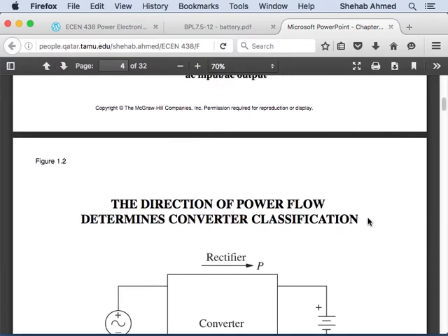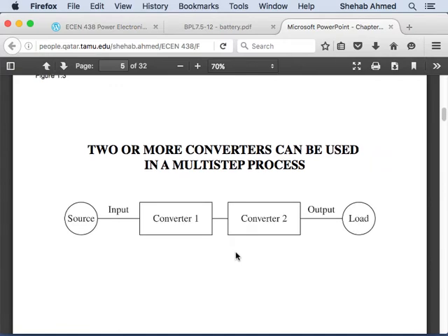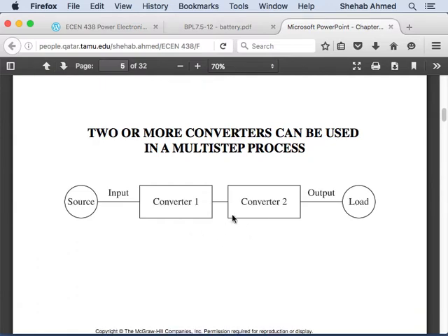Okay. Anyway, as we said, typically we will call AC to DC rectification, and we will call DC to AC inversion. At the end of the day, they're all power converters. That's what we discussed. And we talked about dual stage or series connected converters. So you can have a single stage topology or dual stage topologies. Again, the effect on efficiency is important, but if efficiency is not your only consideration, size, for example, may be important, or cost may be more important. So it will depend on your choice of what you put in there. It will depend on what your metric is.